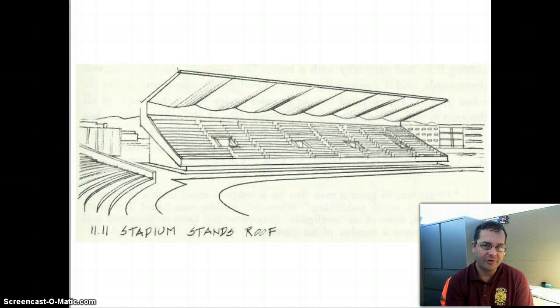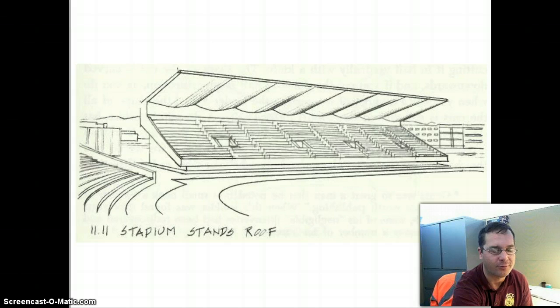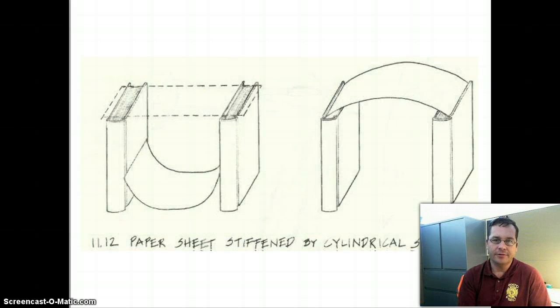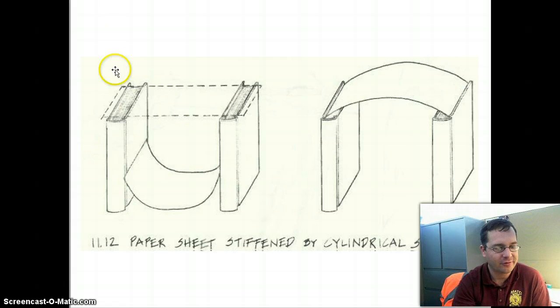Here you see an application of that curve structure to create some geometry to separate the extreme fibers of the material used in a stadium roof. And so this is a reinforced concrete structure that just kind of illustrates how strength can be gained by moving away from the flat sheet and into some type of a curved or folded structure. This is an arch structure, and this is kind of a classical structure in terms of span. It's one of the oldest span structures there are.